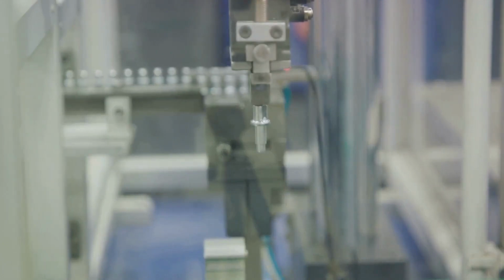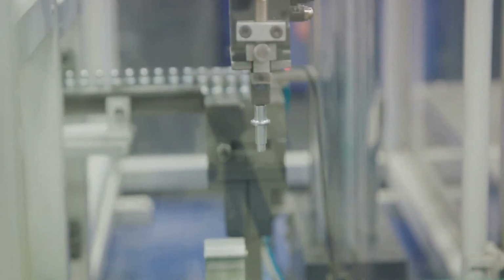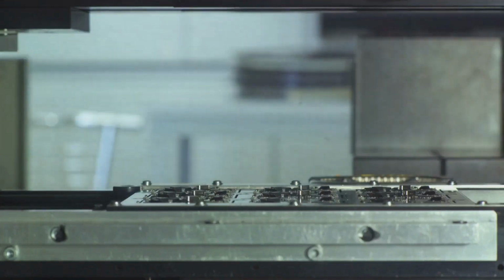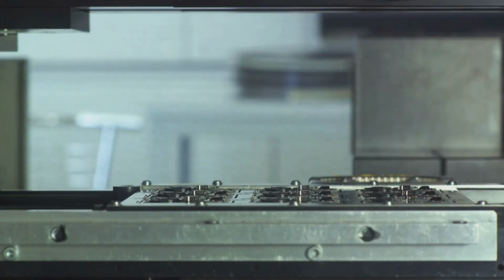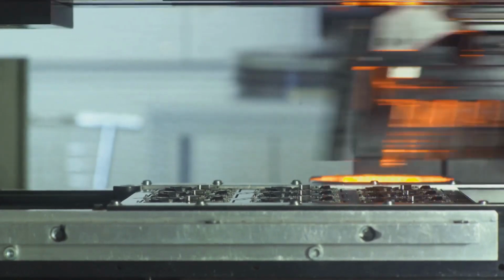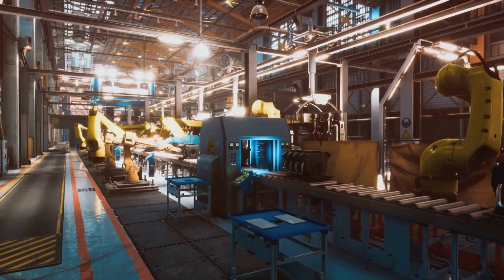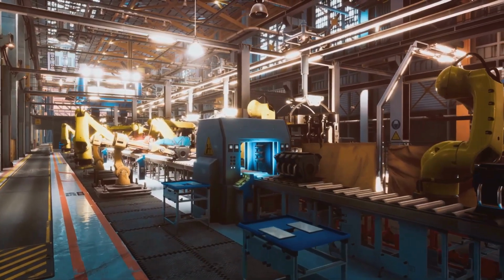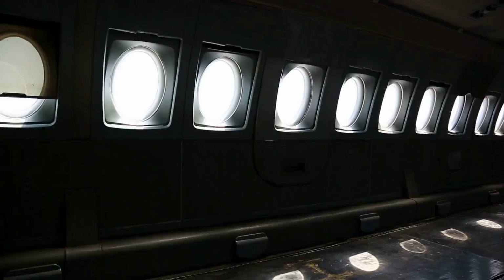With all these parts made separately, you might be wondering how they come together to form a complete aircraft. Well, that's where the final assembly line comes in. This is where the fuselage, wings, tail, and engines are brought together and assembled into a complete aircraft. The process starts with the joining of the fuselage sections, followed by the attachment of the wings. Once this is done, the tail is fitted, and then the engines are mounted. This process requires a high level of precision, as even the smallest misalignment can have serious repercussions.